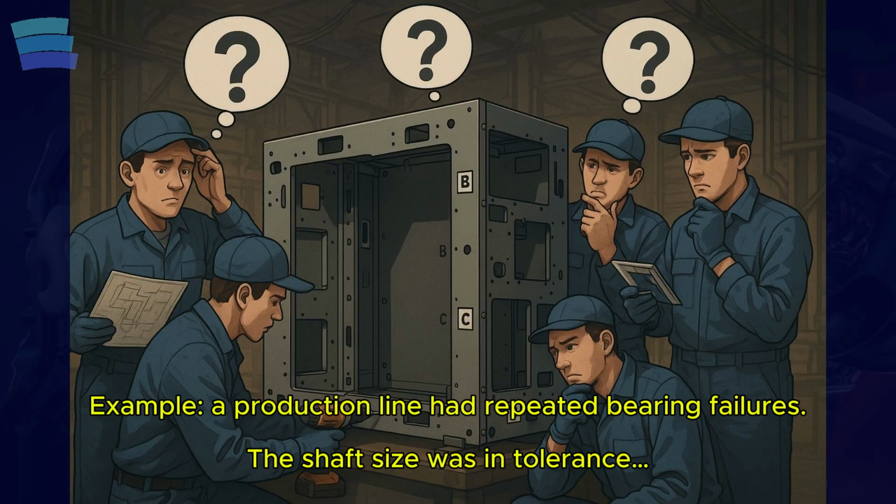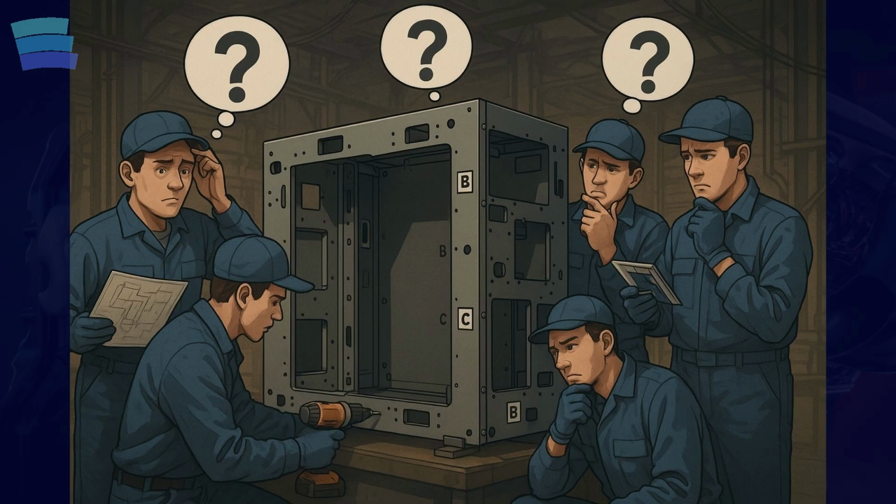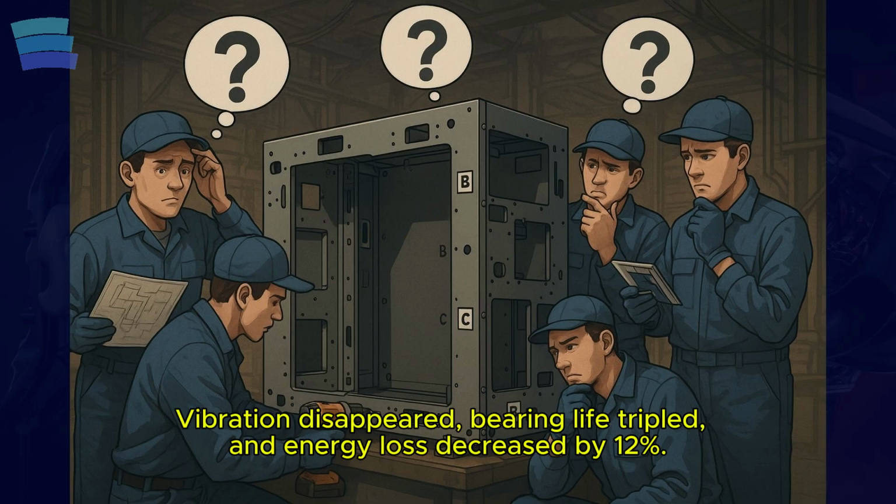A production line is experiencing repeated premature bearing failures. Shaft dimensions are correct, diameter tolerances are within limits. But the shaft axis was slightly bent during grinding. Total deviation was 60 micrometers. When a 20 micrometer straightness requirement is added to the drawing, vibration disappears. Bearing life triples. Energy loss decreases by 12%.